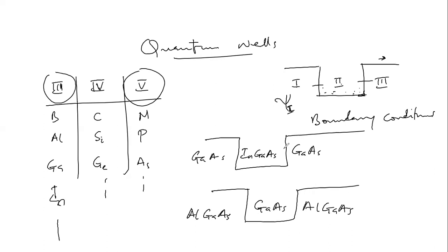Now, why do we want to do this, okay? What was it meant for? What was it used for? Because this process is used for making quantum lasers, okay? We could make LEDs, photodetectors, even high electron mobility transistors. Because at the end of the day, we want to reduce the threshold current required to initiate lasing, like in lasers, thereby making the devices more energy efficient, okay? Such that the confinement of the carriers allows for faster response time, making the quantum well laser suitable for high-speed communication. So we want to do that.